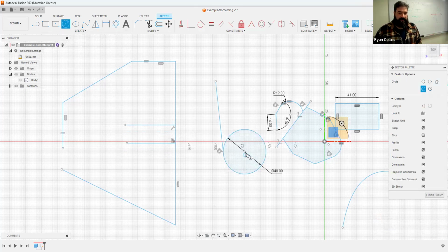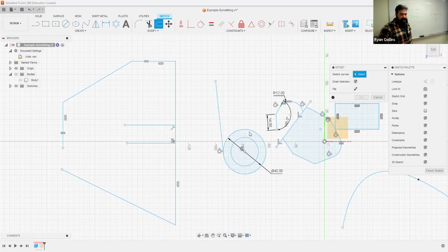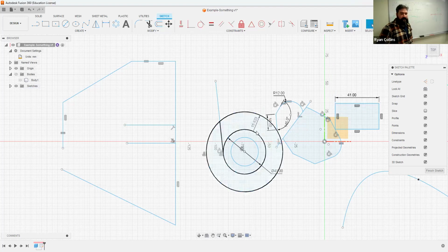Also, if it's a circle, you can just find the midpoint, or the center point, draw it out there. Other thing, if you are making circles, anything like that, really easy to do, use the offset tool. If I want to keep making circles that are based around that first one, use the offset. The only difference is this circle is not 15.8 millimeters in diameter. It is 15.8 millimeters away from that circle. So if I hit there you go. See the distance between there?